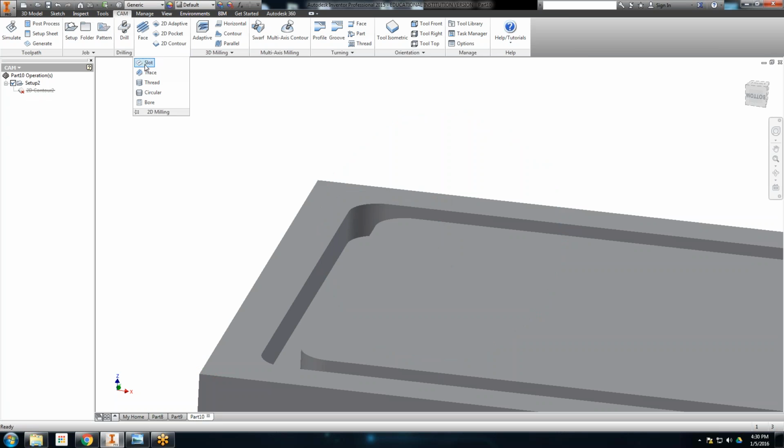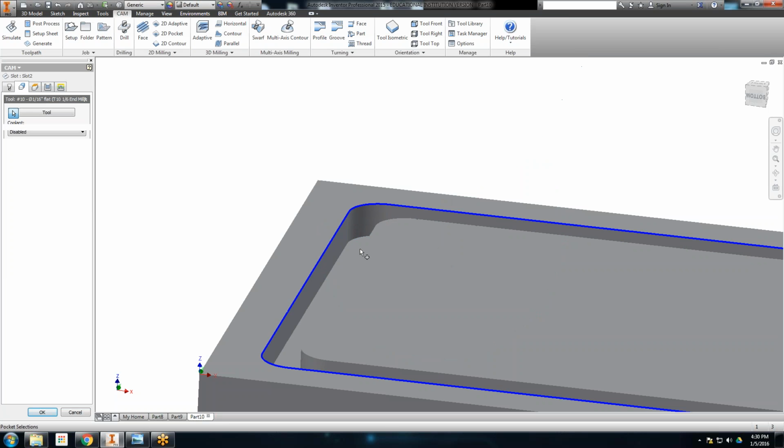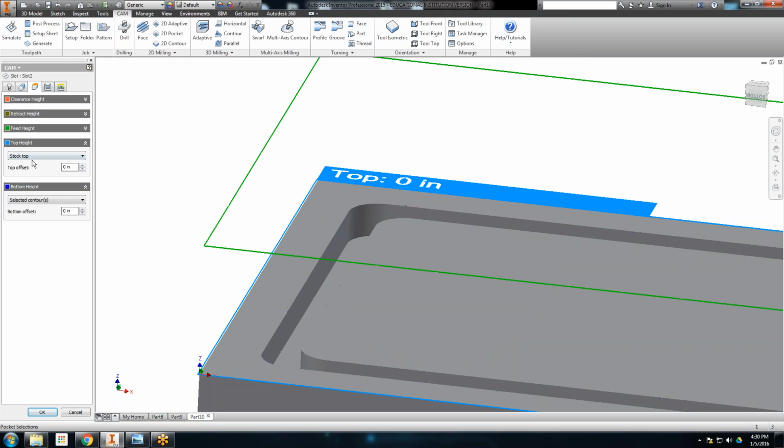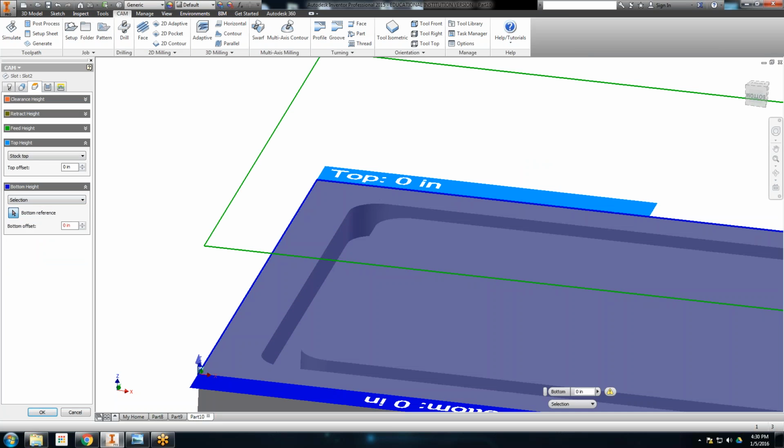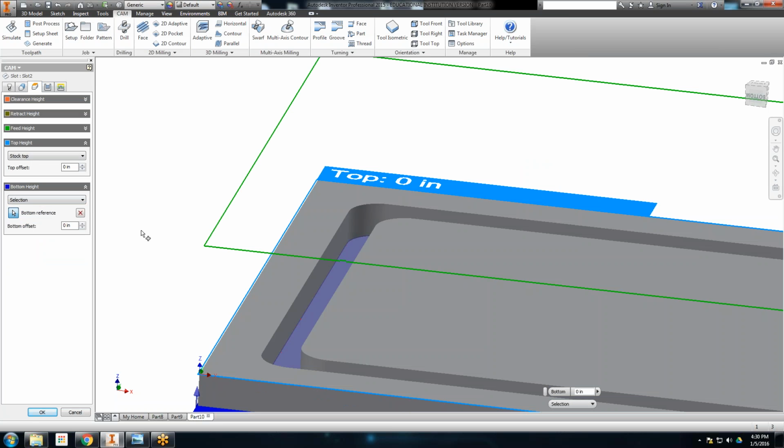So to get it the way it's actually designed, you'd have to do a contour on the inside and the outside edge, 2 tool paths, or I suppose could you also do a pocket on it and have it pocketed out? Sure, but the bad part about a pocket is it's going to wobble. Most pockets do not like, let's say, you have an 1/8 inch tool and an 1/8 inch groove.